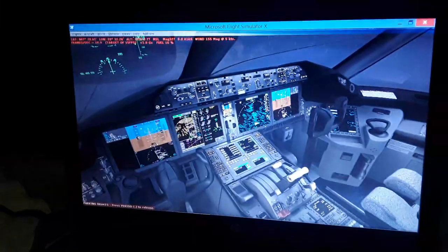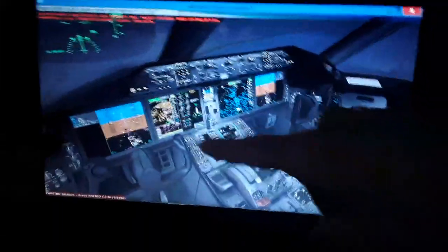It is also the position where the stall begins, where the airflow above the wings of the aircraft starts to become detached from the top surface of the wing. So the center of pressure, and we also have the center of gravity, are around the same position where the aerodynamic chord is, and this is calculated automatically by this computer every time we input the gross weight of